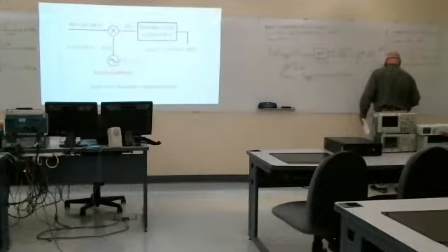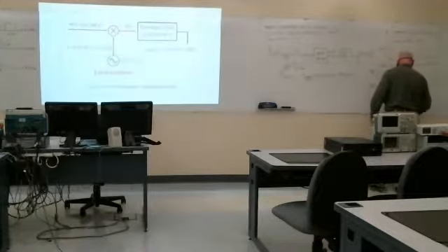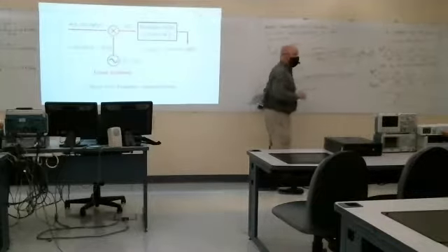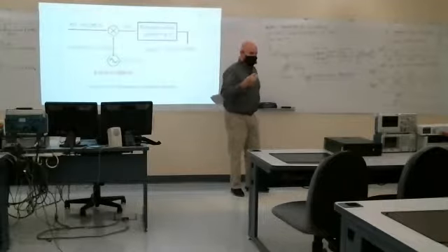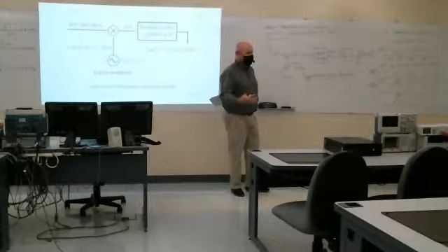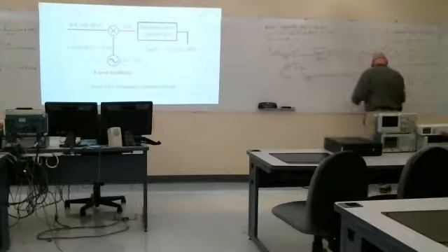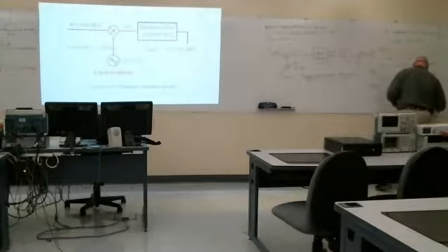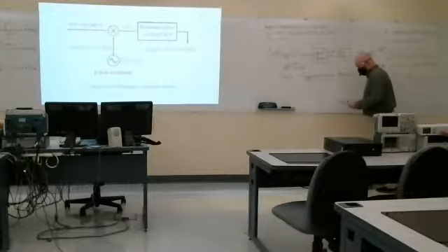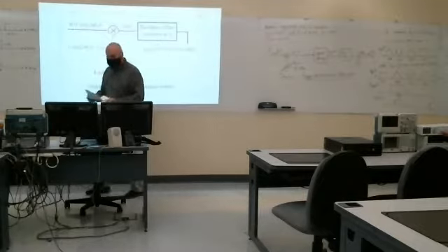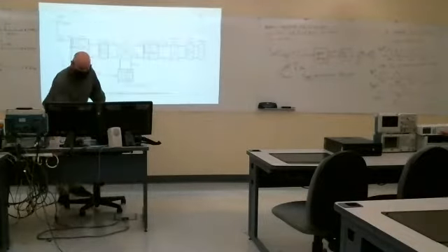So coming out of this, Y2 would always be a signal at 455 kilohertz, regardless, but it would change as we tuned our radio. So this would be Y2 of F. Any questions on that? It's pretty cool, actually, how it works.